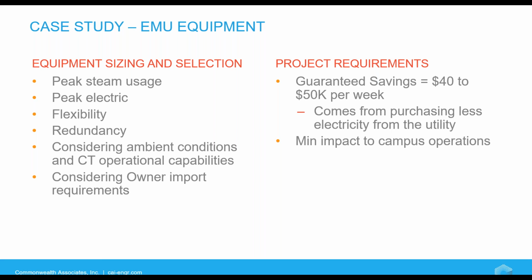Numerous configurations were possible, so they had to investigate if a single generator was sufficient or if 2 CTGs with matching HRSGs would be better to meet load variations and protect against downtime. But in the end, the campus has the ability to draw 100% of its power needs from the grid, so multiple generators were not required.